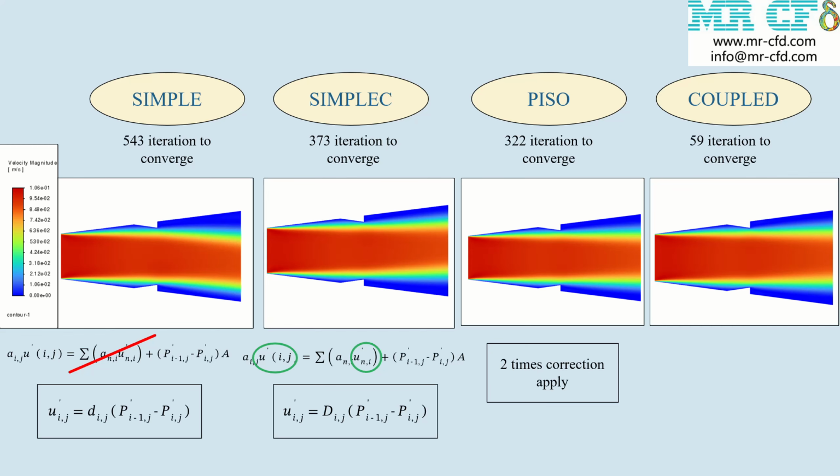In the coupled algorithm, pressure and velocity equations are solved together rather than separately. By integrating pressure into the continuity equation through mathematical processes, all equations are solved simultaneously. Thus, the pressures and velocities from each step satisfy both continuity and momentum equations. This integration enhances convergence speed, as evidenced by its quick arrival at a solution compared to other methods.